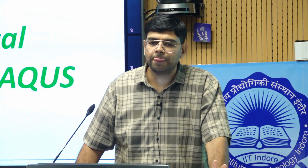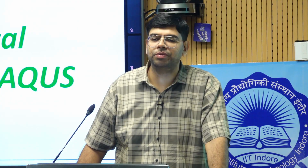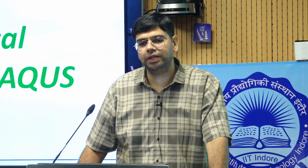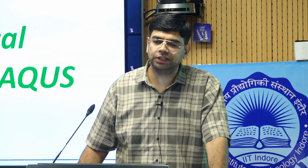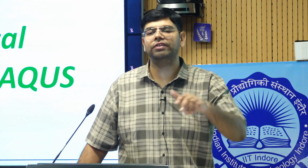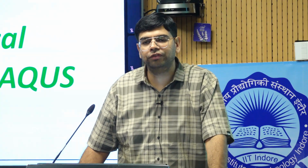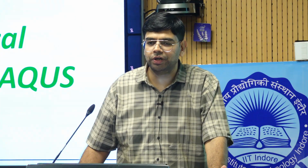So in the last step, the result you have obtained will give you the value of stress, deformation, strain, whatever you want. The stress can be in 3 directions, okay. It can be the displacement or deformation in the 3 directions if you want. So you can define. These are very basic steps you have to follow in any finite element software. I hope you are getting it.